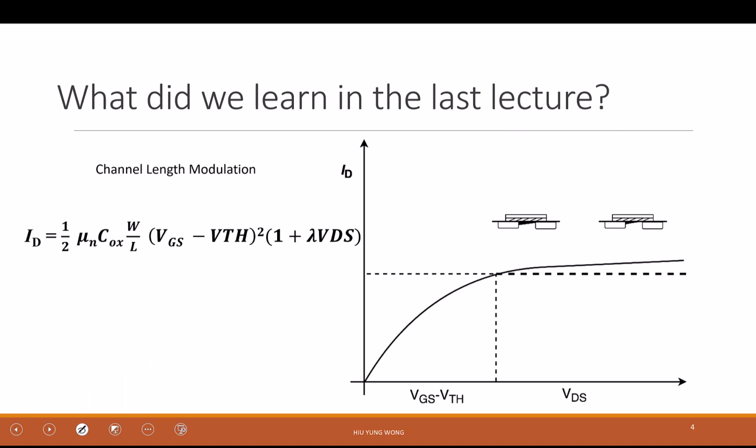So in the last lecture, we talked about the transistor. We talked about the linear mode and the saturation mode, right? You remember when it is in the linear mode? Just a quick review. We know the current is going to be W over L times mu Cox times (VGS minus VT), the whole thing times VDS, minus VDS squared divided by 2.